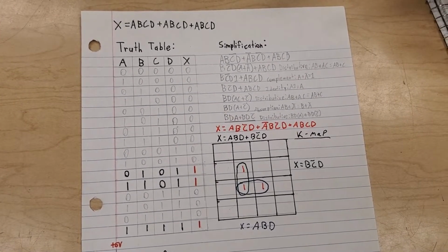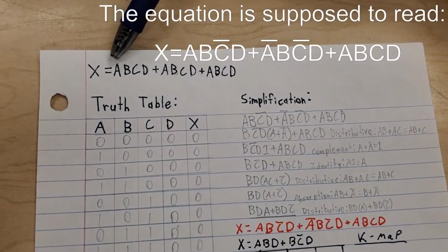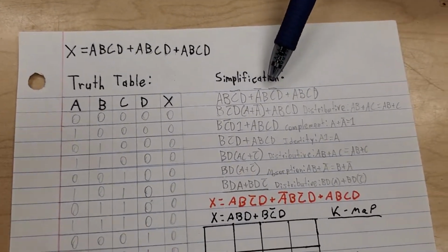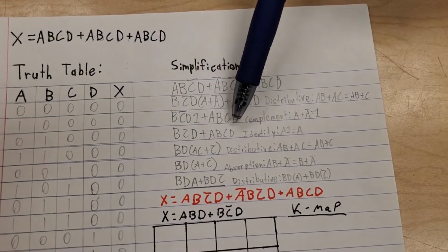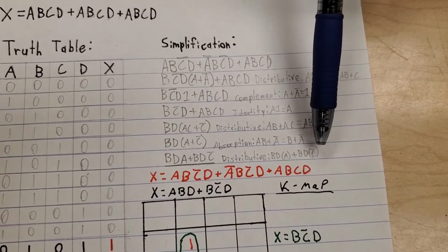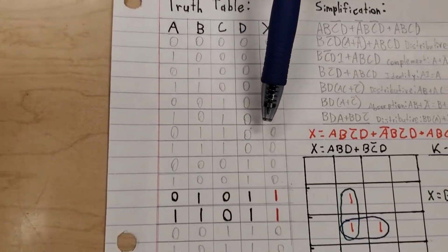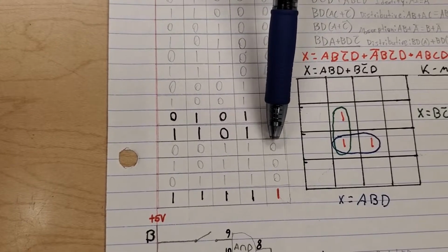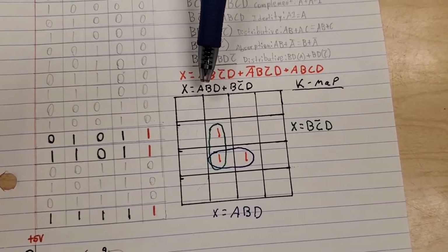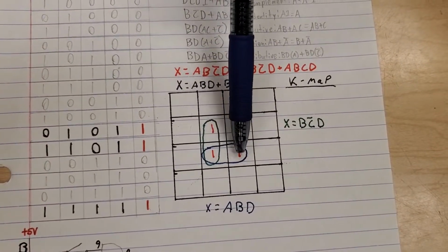This is our digital logic circuit. Here you can see the Boolean equation that we're given for our circuit. Here you can see where we simplified it down to a simple equation. Over here you can see where we worked it out in a truth table. And there's only 3 times where the circuit is logically true. Here you can see our K-map that we drew of those truths.